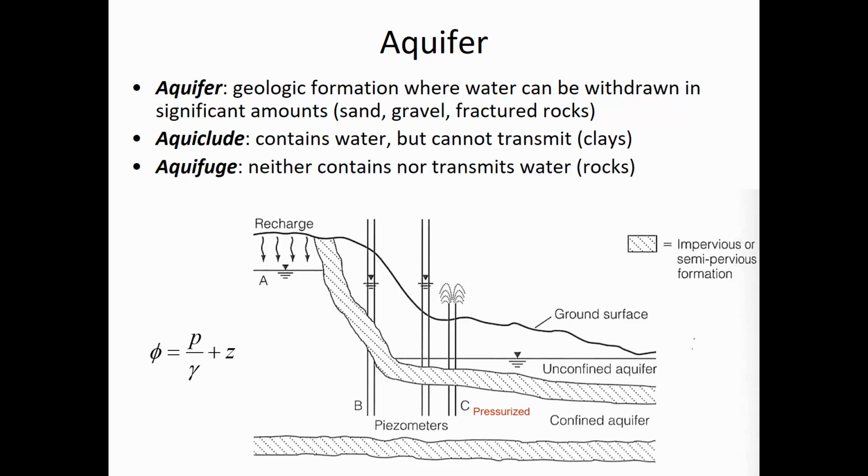confining layer beneath it. Throughout the earth, there could be layers of relatively high conductivity sand, and then a layer of clay, and then silt, and then more sand, and so there can be a series of lots of different aquifers. You may have to penetrate down through several different aquifers before you get to one that has the water characteristics that you'd like, for example.